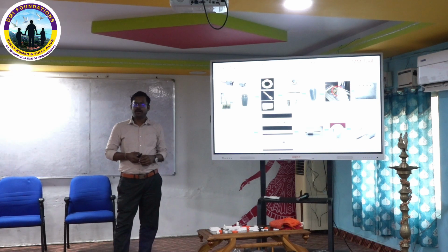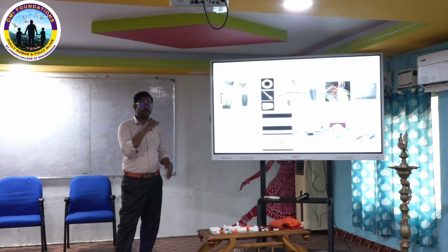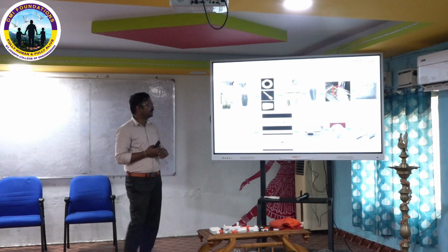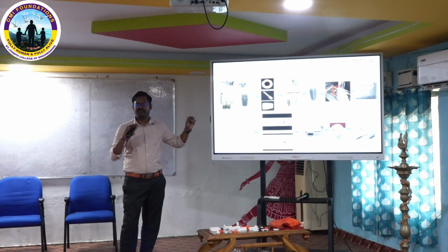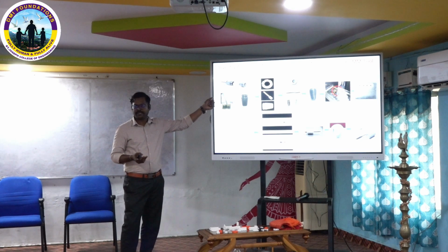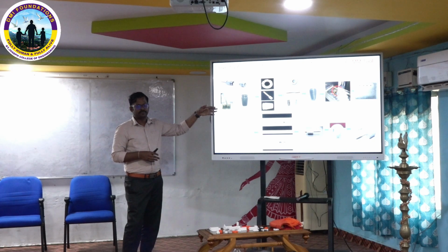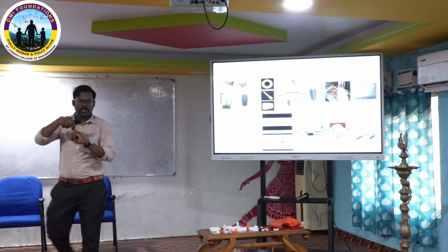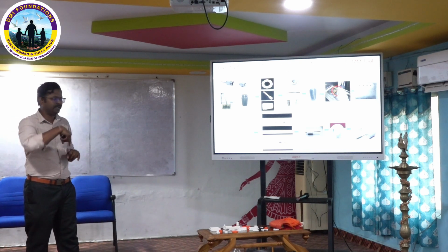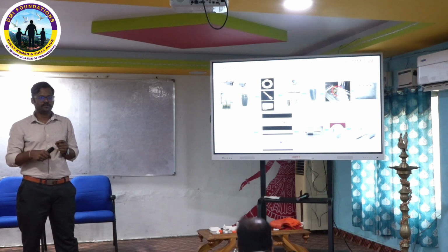with acetone. In my ME work, I planned to replace that with additive manufacturing. I fabricated it with ABS. I did reverse engineering here with a simple vernier caliper. I measured all the data, designed the samples and fabricated them. But the main problem I faced here is conductivity, because the tool holder's job is twofold. One is to hold the tool and move with the bed. The next is to conduct electricity from the machine to the tool.